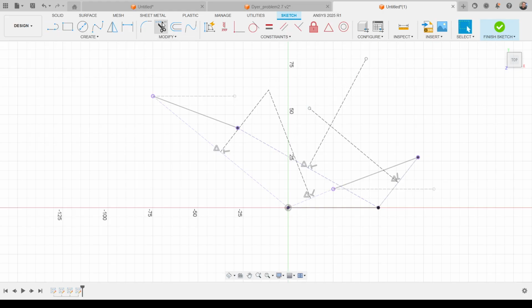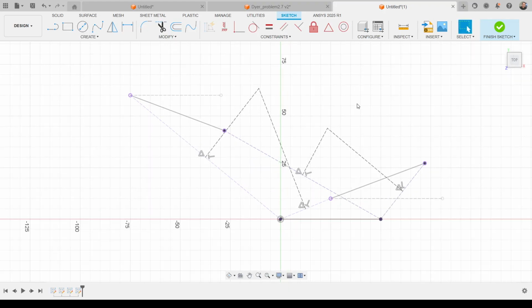The symbols are there, showing me that I created these two bisecting lines correctly. Okay, so now I have the regions for link number 2 and link number 4 defined. I can come and attach those two origins, and the next step will be creating circles that go from here to here.